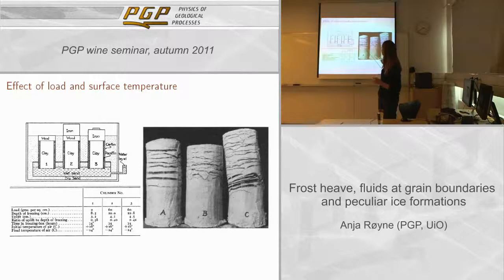there's more water in this column now than it was when it started freezing. Because it doesn't match basically with the expansion. So that means that the only place the water could have come from is the bottom. So it means that as this was freezing, it was pulling water in from this wet sand underneath. And that's related to the temperature gradient.